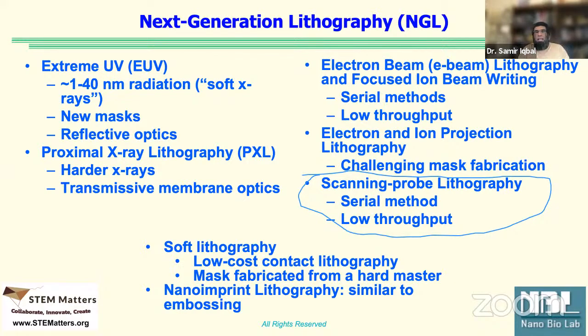Then towards the end of this module, we'll go into soft lithography. We take the word lithography from this concept of transferring patterns, but we will be dealing with soft materials and writing in soft materials directly. Those soft materials, or what you call polymers, you can call them plastics, but polymer is more appropriate.